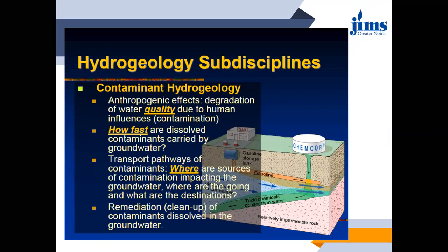If they are inorganic, there is no need to remove them. They don't cause contamination, they only cause turbidity, which is removed. If there is contamination due to organic impurities, then self purification is a natural process. Dissolved oxygen, BOD, and microorganisms take care of the organic matter.